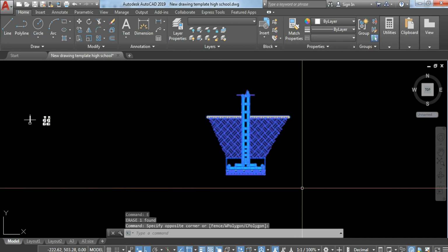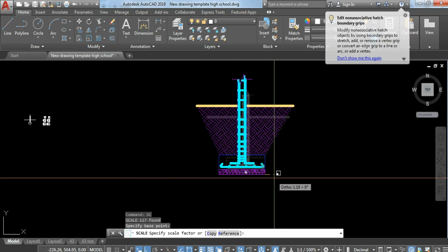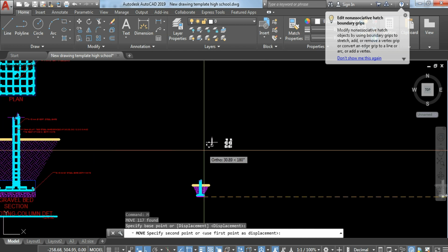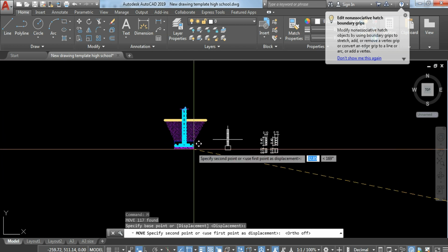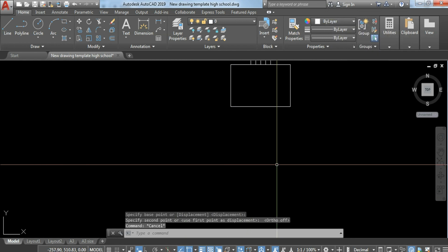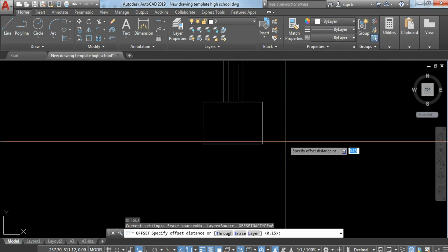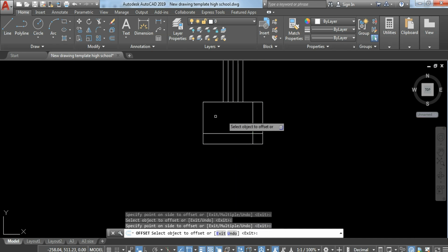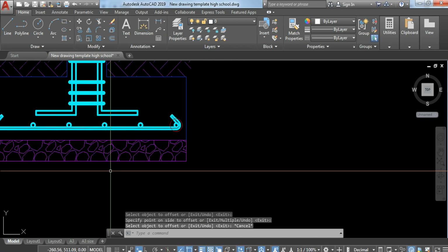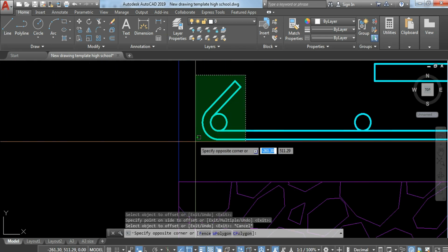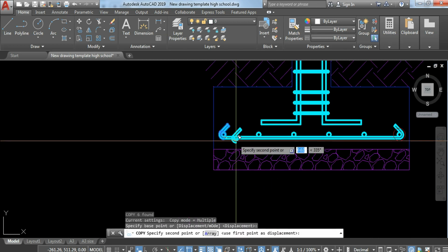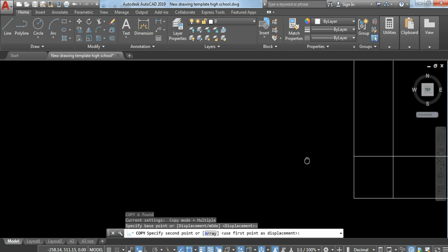Okay, so I'm going to rescale this scale. Since this is a 20, ang itatype ko dito 20/100 so that I could go back into 1:100. And I'm going to move this drawing somewhere here closer sa ating drawing so that I could copy all the important points. So here, I'm going to offset at 0.05 on both sides. Here, here, and here. Okay, so after dito, I'll just copy this one, this layout here, copy, and then place it somewhere here.